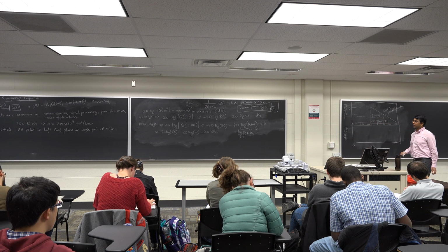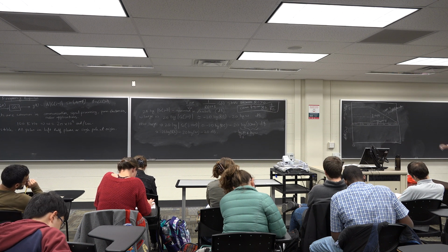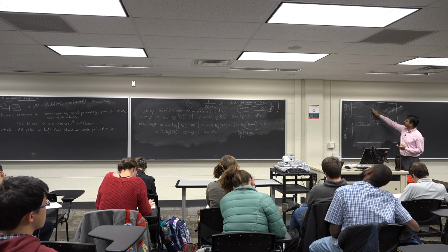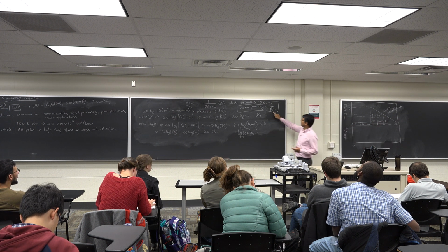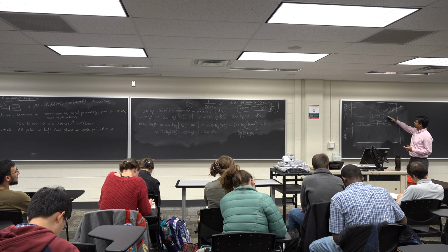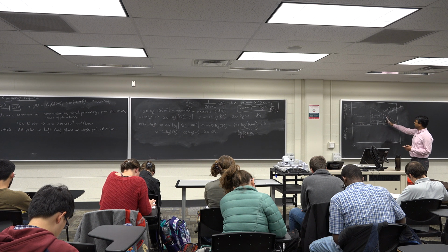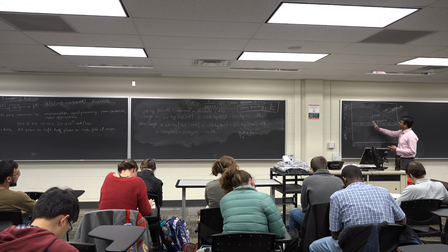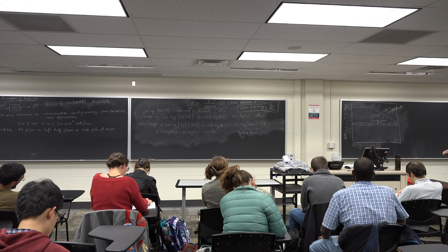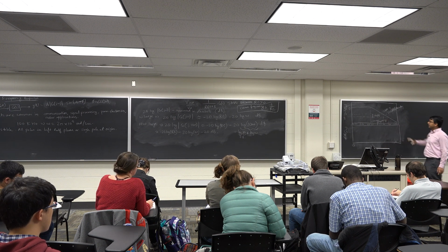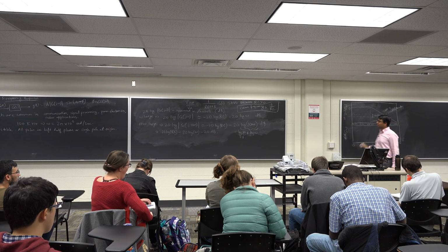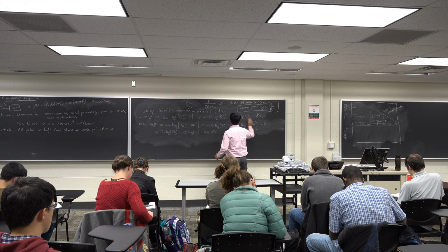Now we haven't plotted the phase diagram, but we are going to get to the phase diagram now. By looking at the log gain diagram, there are many things we notice. We notice the corner frequency at which the slope changes. The corner frequency for this particular system is 1 over RC. So that's where you see a change in slope. You see an asymptotic slope of minus 20 dB per decade for very high frequencies. And for very low frequencies, the log gain is almost 0 decibel. So those are the 3 things to remember from this log magnitude graph of the Bode plot. Now we look at the phase angle of the Bode plot. So let me erase this part.